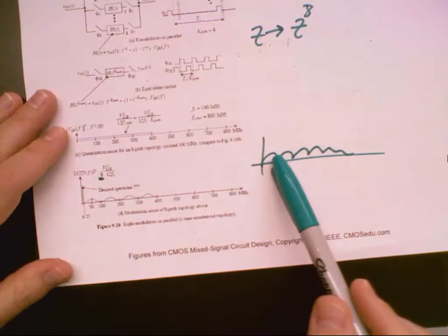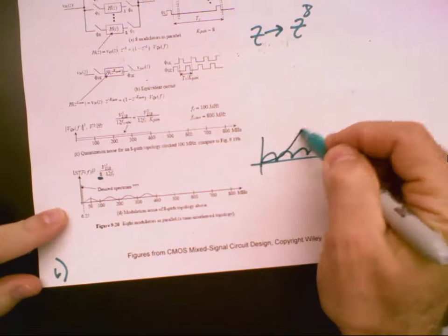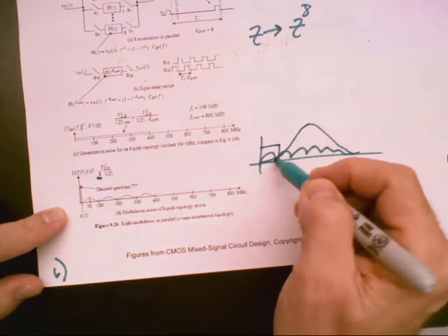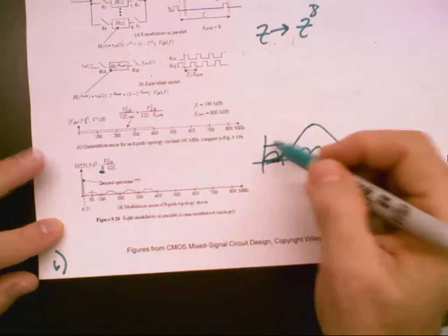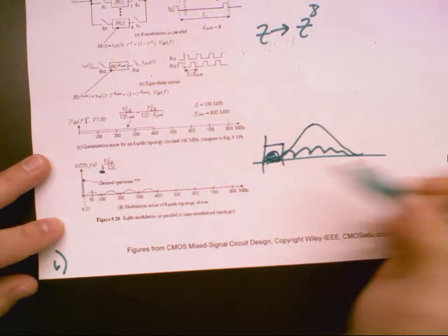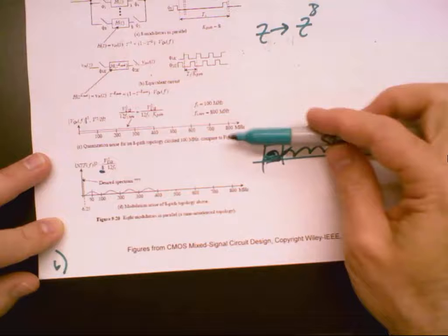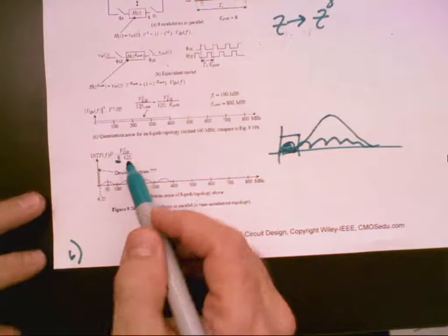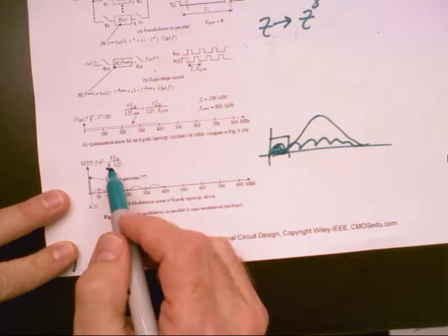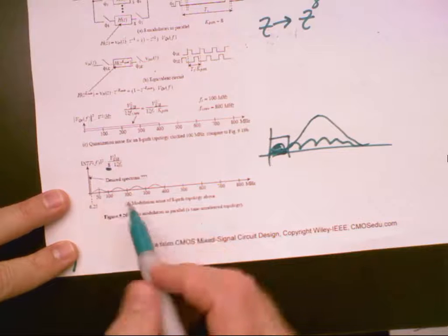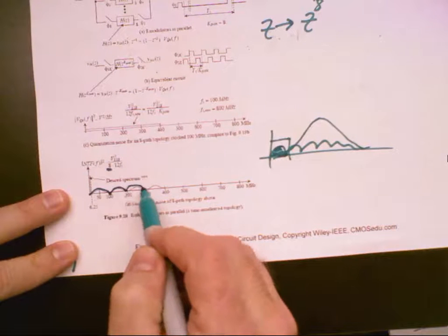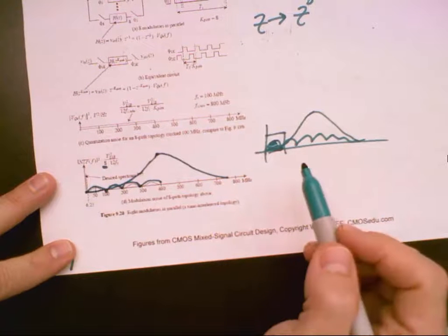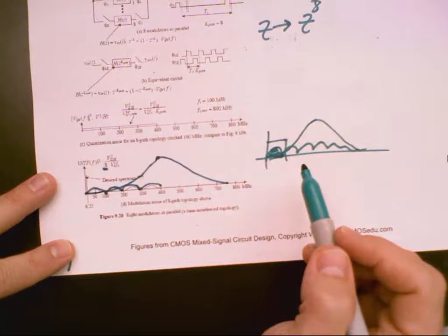What we want is noise that does this, so that when we pass the signal through our filter, we have less noise. What we have when we do this is the comb filter where it repeats, and we still have significant noise there. In other words, by putting multiple paths in there, we reduce the peak quantization noise by the number of paths in parallel, but we still get the rippling effect. We don't get true noise shaping, which does this and repeats at f sub s nu. Does that make sense?